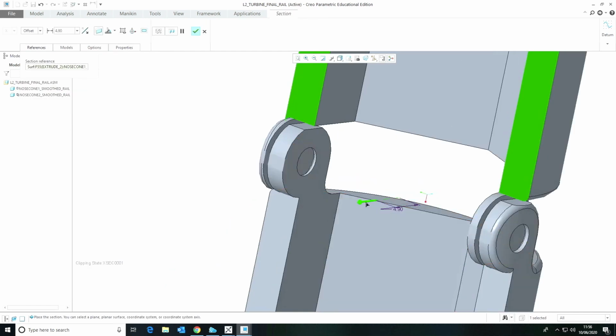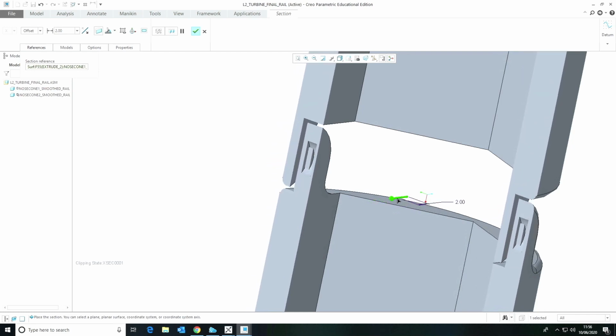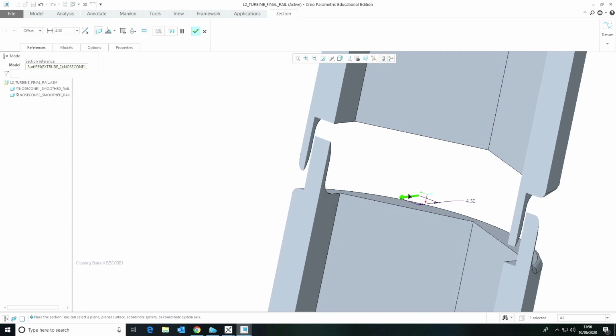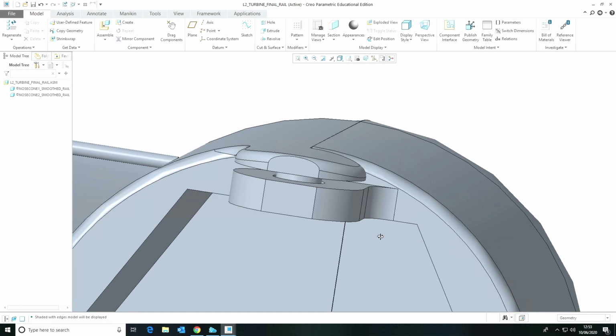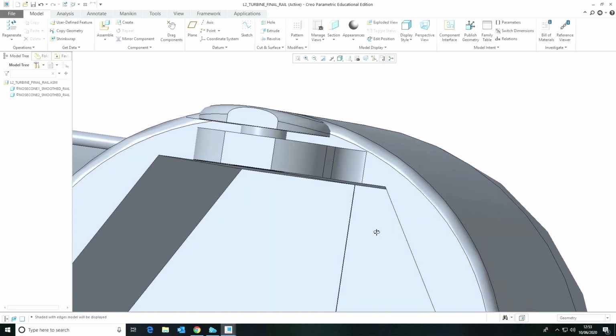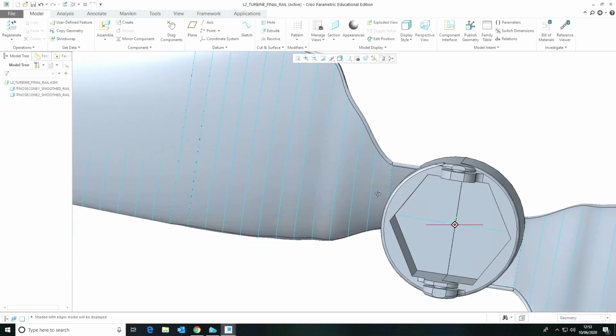The hinge was of a simple ball-and-socket design, with as much clearance as possible between the moving parts to minimise the chance that the hinge would get fused together during printing. The external face of the hinge was also shaped to follow the contour of the nose cone, and the entire hinge was designed to be as small and discreet as possible to minimise its effect on the aerodynamics of the turbine. A small 1mm diameter rail was also added to the trailing edge.